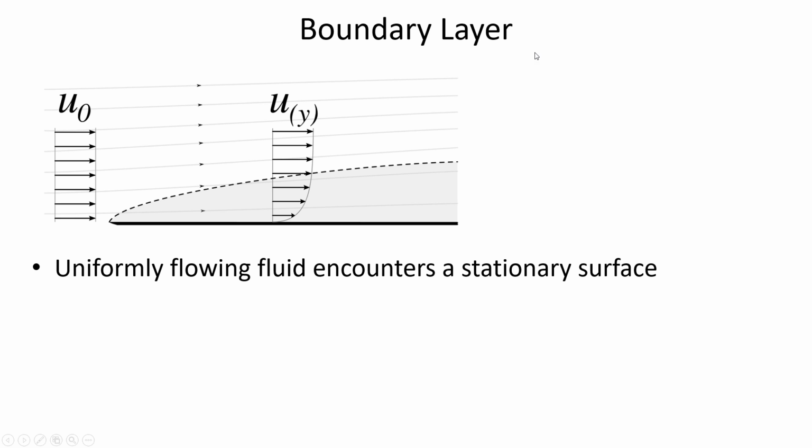And that's going to be important to us when we talk about estimating energy losses, is the thickness of this boundary layer. A boundary layer is just, you can think of it as a cushion, where the flow conditions are a little bit different than in the majority of the pipe's cross-section. Like if the water is flowing around at a uniform velocity distribution, so this is showing that, if we take a side view, and here's a piece of material. It could be a sheet of metal, for example, or it could be the boundary of a pipe.